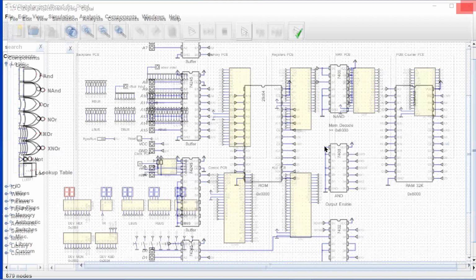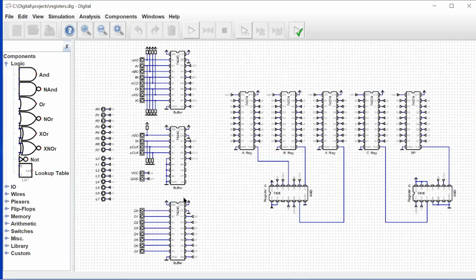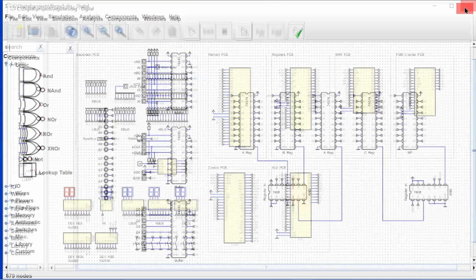All right. The registers, same thing with the registers. Again, the 245s as input buffers. These registers should be sufficient to drive the outputs directly, so we're not going through 245s for the register outputs. All right, and again, heavy use for the tunnels.